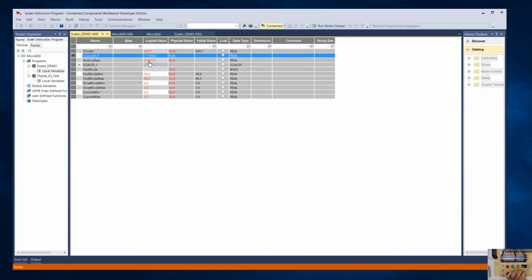So see here, as this analog real creeps up to 30, right when I get to 30,000, I hit my expected 10, but then even though the analog real continues increasing, my actual output is held at 10. So that's a way to just programmatically ensure that you don't get values you don't expect.